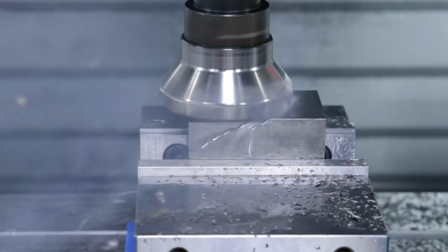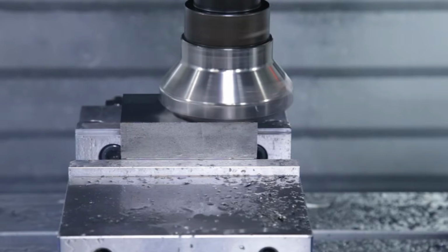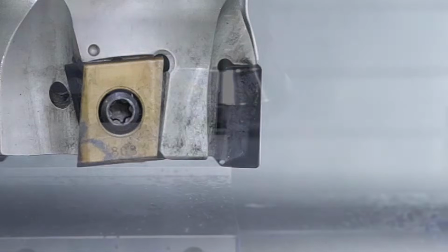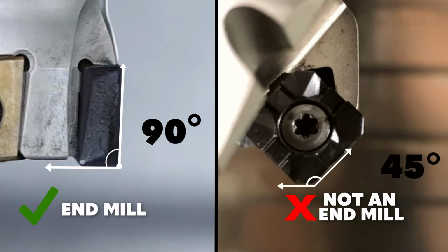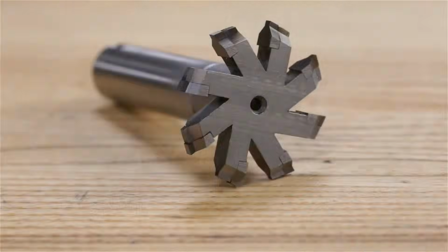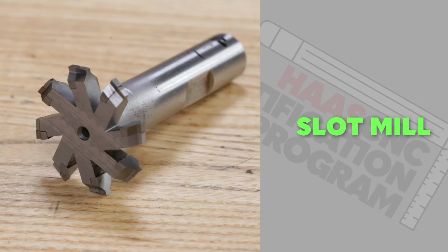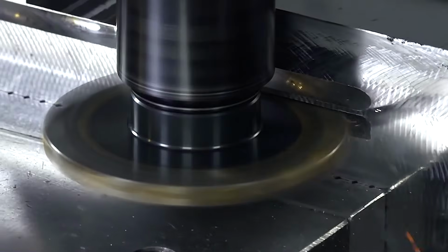Now, the best way to tell the difference between an insert end mill and any other type of insert cutter is to look at the side of the insert. If this is 90 degrees to the bottom, it's an end mill. If it's not 90 degrees, it's not an end mill. Now, this cutter is called a slot mill. This particular one has a specific form on it for making the slot in the side of a part.